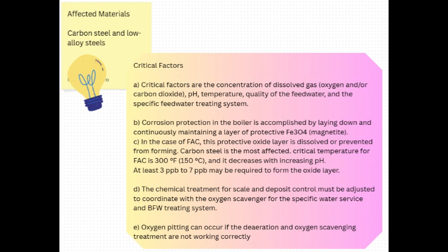Okay, what else? pH is huge. The corrosion rate drops sharply as the pH goes up. So alkaline conditions are good. High pH protects against FAC. Absolutely critical. Keeping the feedwater pH high is a primary defense against FAC. So just to summarize FAC, it's not just rust, it's the protective layer getting stripped off, mainly around 300 degrees F, and it gets worse at lower pH.